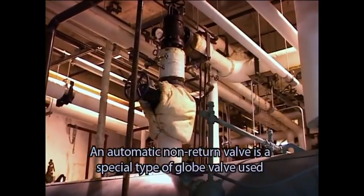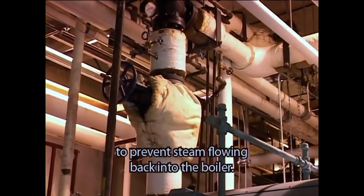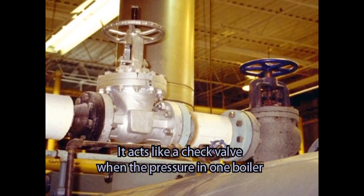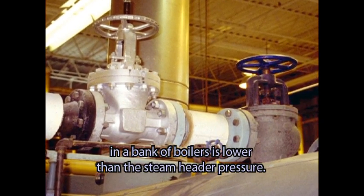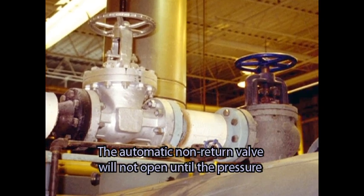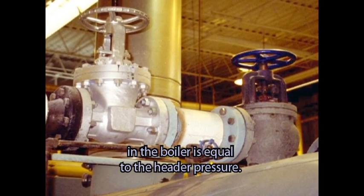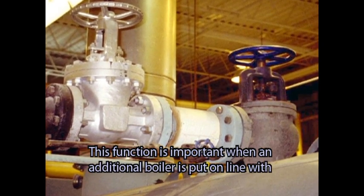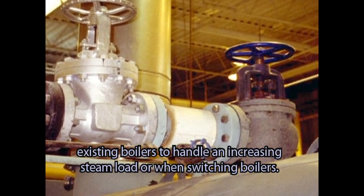An automatic non-return valve is a special type of globe valve used to prevent steam flowing back into the boiler. It acts like a check valve when the pressure in one boiler in a bank of boilers is lower than the steam header pressure. The automatic non-return valve will not open until the pressure in the boiler is equal to the header pressure. This function is important when an additional boiler is put online with existing boilers to handle an increasing steam load or when switching boilers.